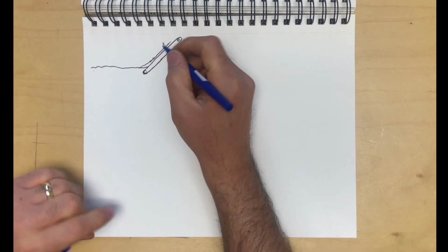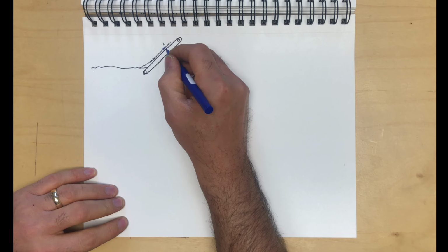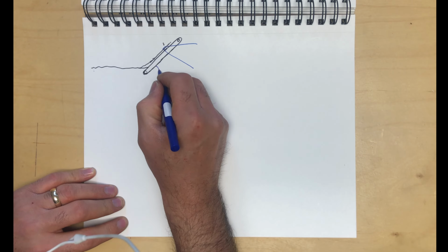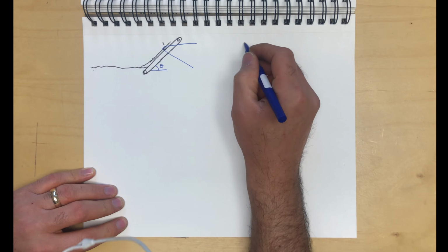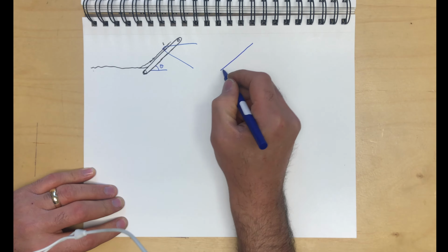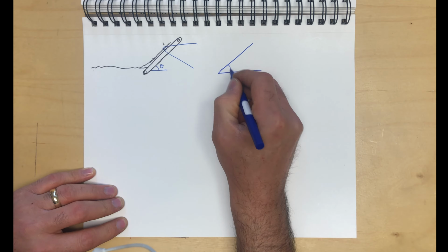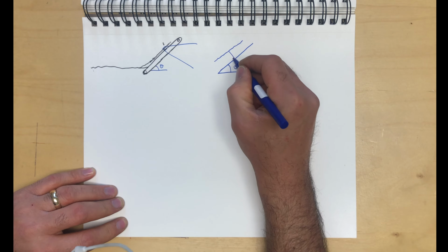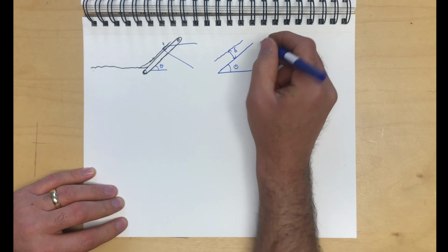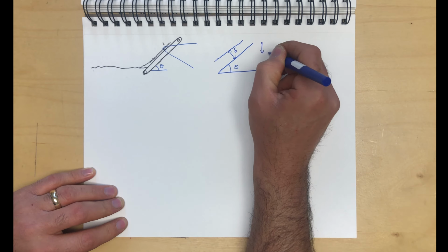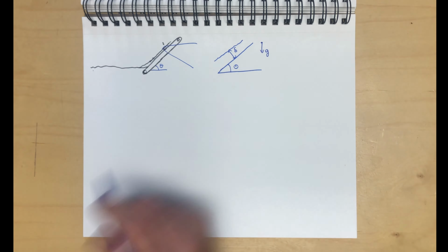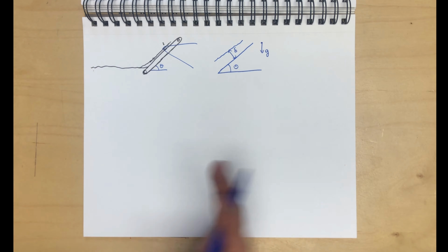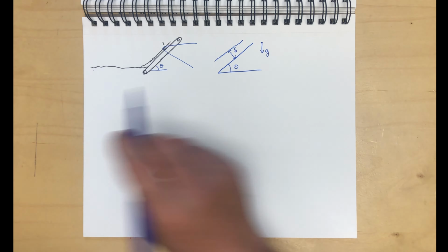So we are going to focus on modeling this particular region of the flow. So this is inclined at an angle theta. So we have this configuration over here, and we have some liquid at a thickness delta, and gravity is acting in this direction, so that the individual components of momentum are going to have a gravitational component.